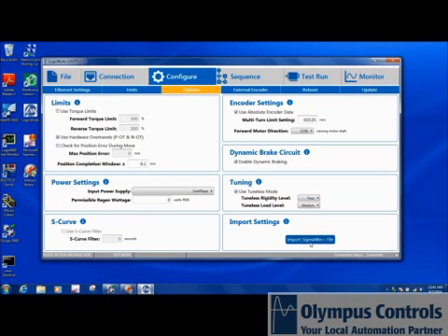If I want, I can use their Sigma Win software, which is a real high-end configuration and PID tuning utility that lets you get into all the nuts and bolts of the drive and use an oscilloscope to tune and get things tighter. But typically it's not required. You can even have a system with up to a 20-to-1 inertia mismatch with the load, the rotor to load inertia ratio of 20 to 1, just using the built-in tuning that's in the auto tuning inside the drive.